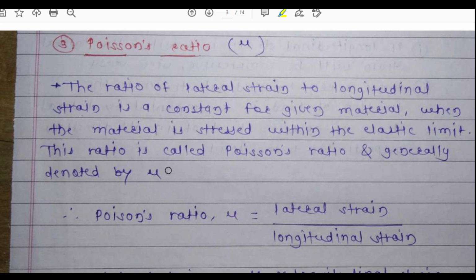Now here it is not necessary that the lateral strain should be in the x direction only. That can be in the y direction also, because if the force is applied from the y direction or from the z direction, then the longitudinal strain will be in the y direction or the z direction. And exactly opposite, when the force is applied in the y direction, the lateral strain will be produced in the x direction.